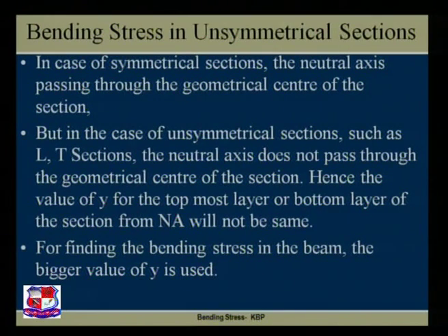Hence, the value of y for the topmost layer or the bottommost layer of the section from the neutral axis will not be the same. What happens up till now in the problems is that as the neutral axis passes through the geometrical center, y_B and y_T remain the same, but in the case of unsymmetrical sections this doesn't remain the same.